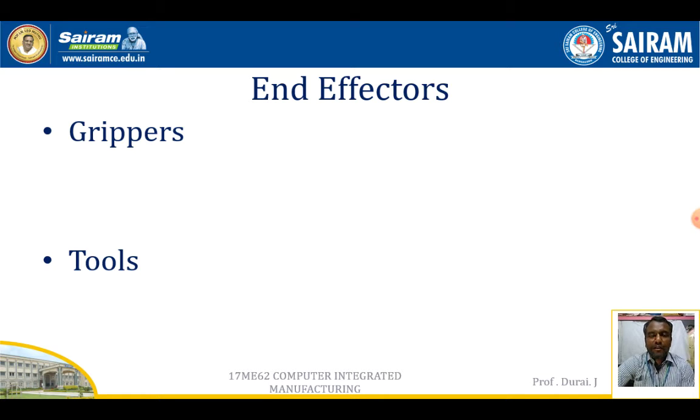Usually in the electric drives, two types of electric drives are used: direct current servo motors and direct current stepper motors. These DC motors can provide small volumes and high torque, and they are precise, clean and reliable. The torque produced is proportional to the magnitude and direction of the current flow in the rotating armature. So the electrical energy is converted into useful mechanical energy.